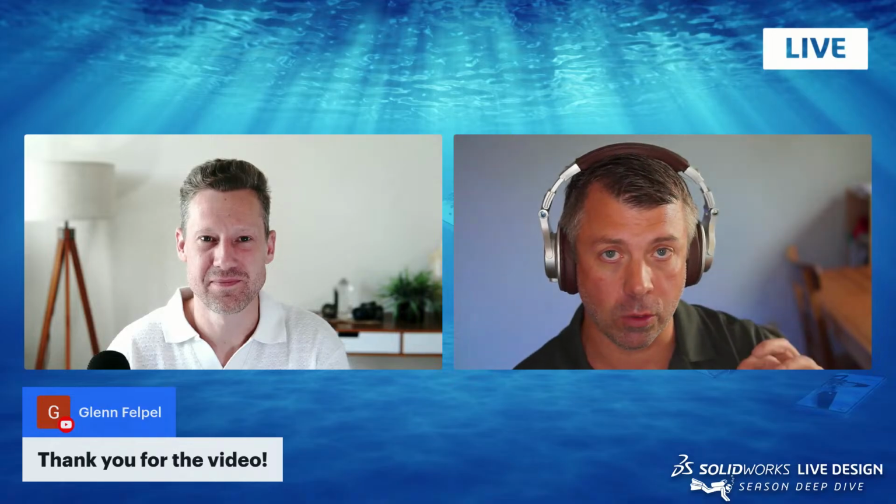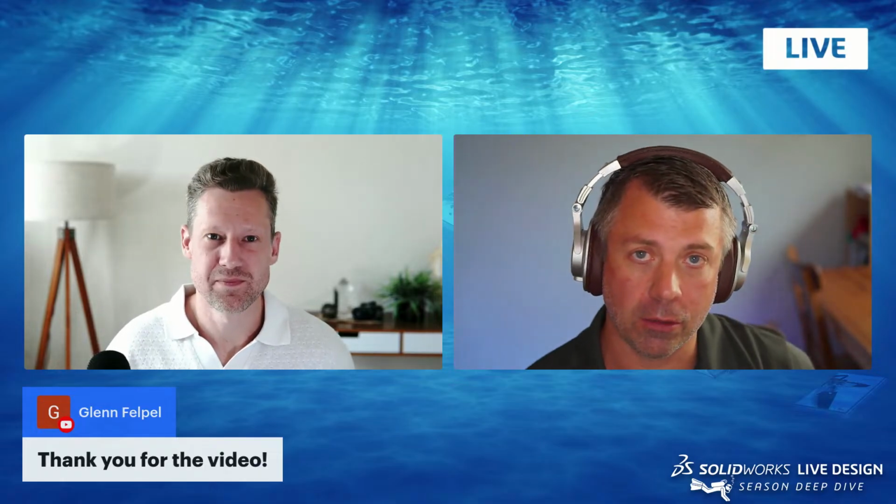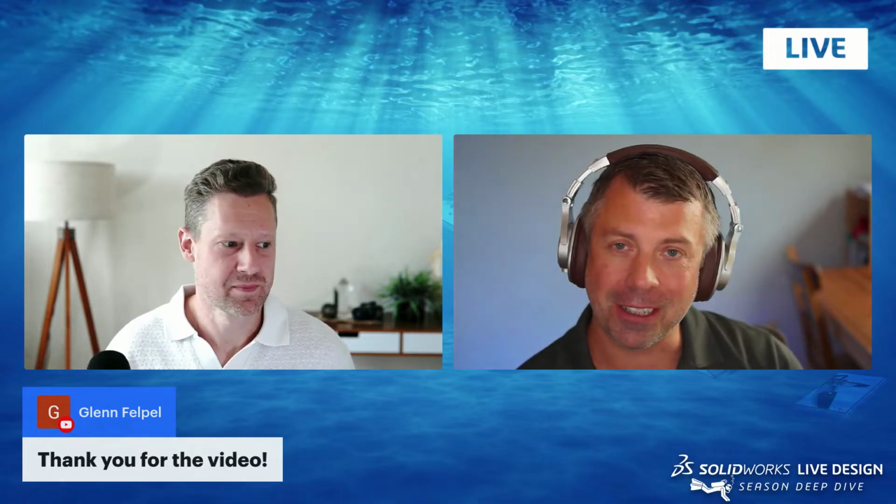Mark, this was awesome. I took a bunch of notes because I learned a bunch of stuff, and I'm going to review those with everyone. So big takeaways for me: starting with relationships first, starting with large dimensions and going down. So define your relationships, right? Pay attention to the icon, the color of those relationships as they're created, yellow and white. They mean different things. So that's a really awesome tip. A for alternate, not arc, because that's what I always think. So that can be used as a hotkey when you're drawing to switch between the types of rectangles you might be creating. Also, change from arc to line. Equal-sided rectangle. I love it.